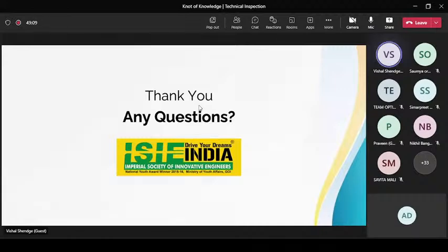About the brake light: it must be red in color, clearly visible from the rear, located on the vehicle's center line. The brake light must be round, triangular or rectangular on a black background, 50 centimeter. Sufficient brightness for visible activation in bright sunlight. These are the rules about the brake light.